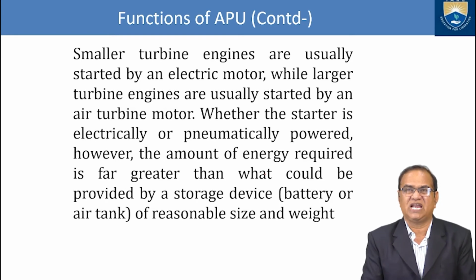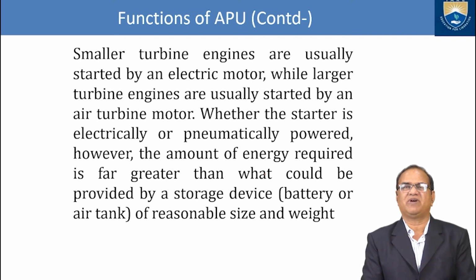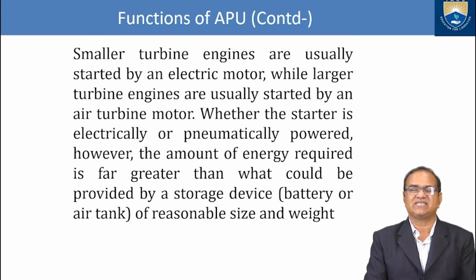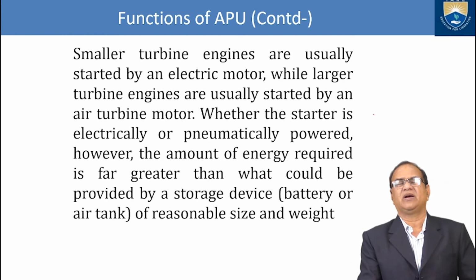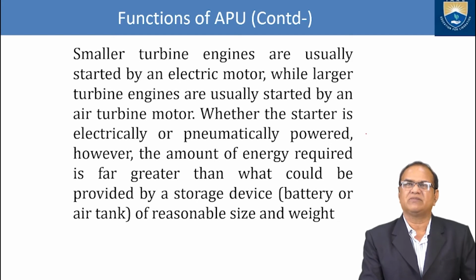Whether the starter is electrically or pneumatically powered, however, the amount of energy required is far greater than what could be provided by storage devices, a battery or an air tank of reasonable size and weight. So for a bigger aircraft where big engines are used, electrically rotating devices are not sufficient. So we need some device that is called the auxiliary power unit.